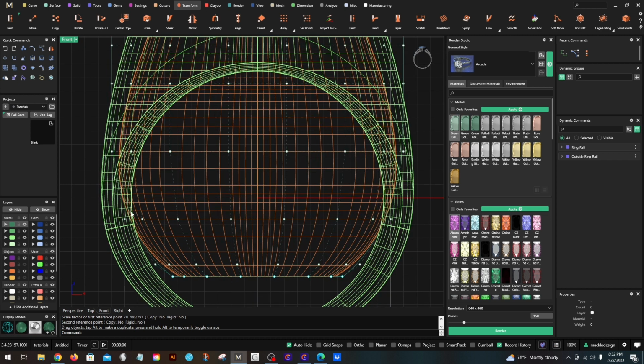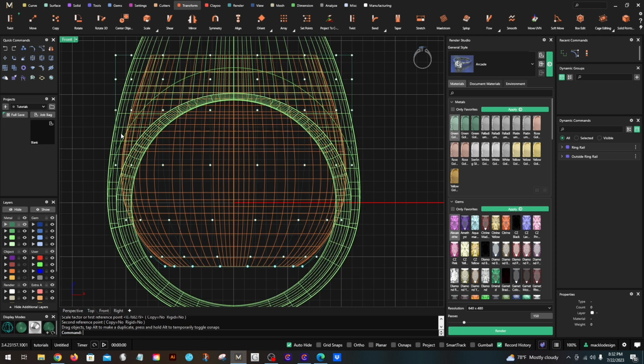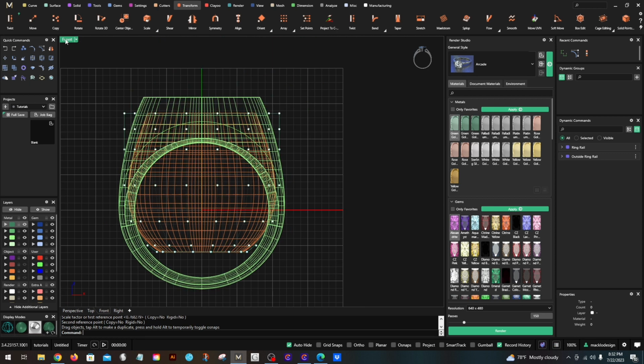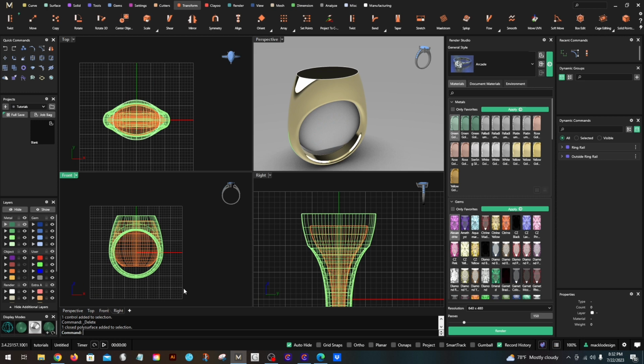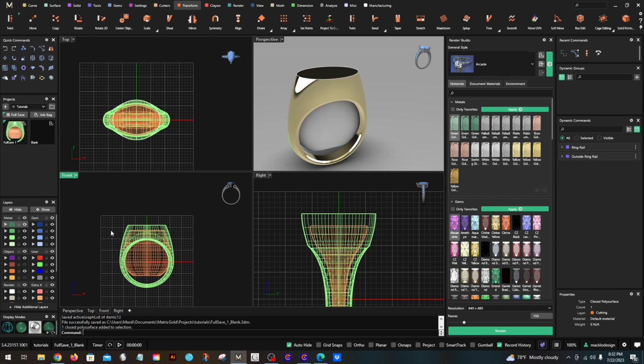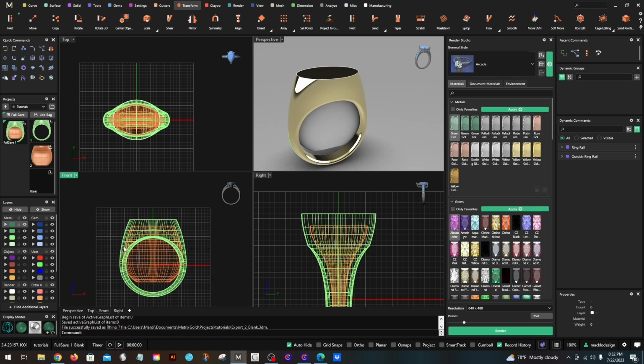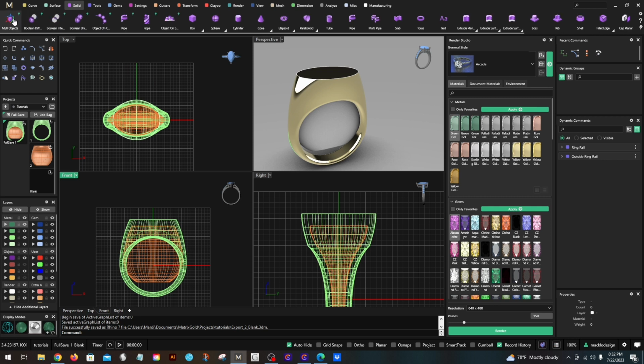So see how nice the cutout's going to be? It's going to just kind of flow right off of there. Okay. I can delete my control box, and let's go ahead and full save this. Sometimes what I'll do too is I will save my shank and ring in the job bag and the cutter separately, just in case something weird happens. You never know. All right, Boolean difference, select my first surface, select my second surface, and there we go.